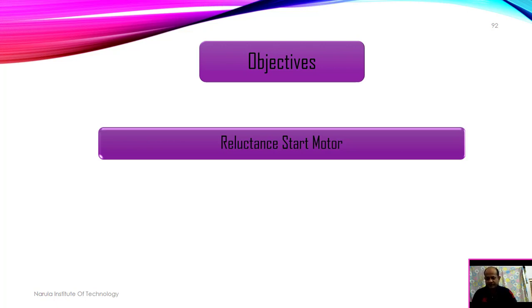One is the main flux and one is the short circuited flux which flows through the shaded pole. These two fluxes have a time difference as well as a difference in space, and for that we are able to produce a very poor rotating magnetic field, and provide the starting torque in the case of the shaded pole.